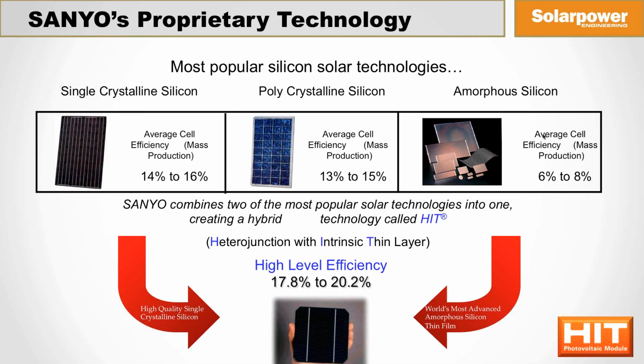this temperature performance. And it all goes back to this well-known fact in solar that at solar noon on the hottest day, where you think your production is going to be the greatest, you're actually starting to degrade due to temperature. The temperature coefficient is a negative number that you apply for every degree above 25 C or 77 degrees Fahrenheit. For the ambient temperature, the truth is a solar panel, wherever it is, whether it's on a hot roof or out in the desert in a ground mount, the nominal operating temperature of the cell is actually going to be a lot higher than 77 degrees when the ambient is 77. So that's when it's time to apply this temperature coefficient.